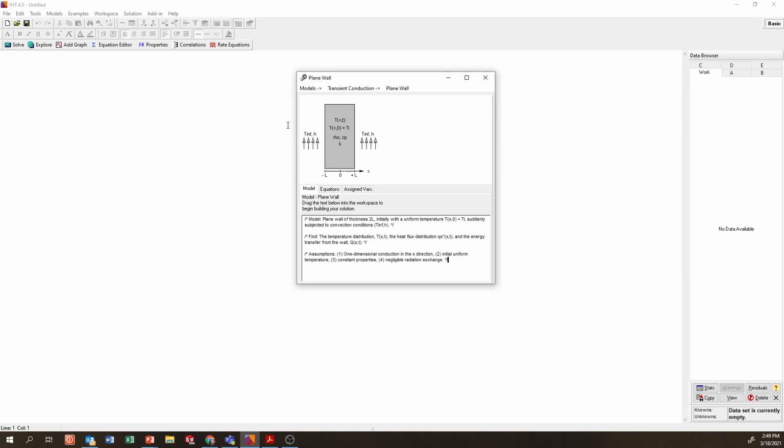So we'll have to think back to our earlier discussions. If we think about that, we decided that if the cooling is truly symmetric, right in the center we're going to have no heat transfer from the right to the left. So in that case, when we have the single side, we're just going to double the L value to get that full thickness, and cooling only on one side is like it's insulated right there in the middle. So we're going to double that L to kind of trick it into thinking it's only cooled on one side. So I'm going to grab these properties or the comments here.